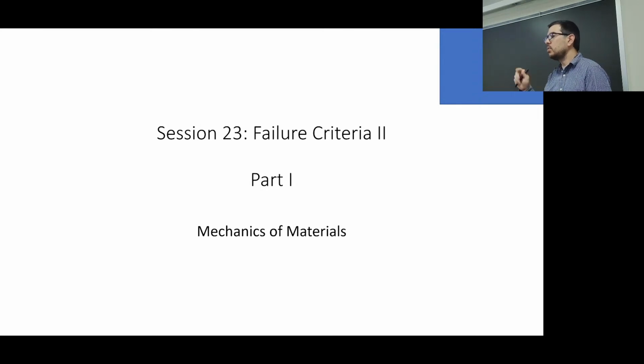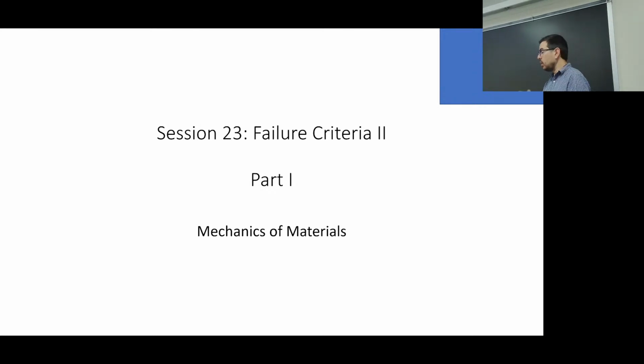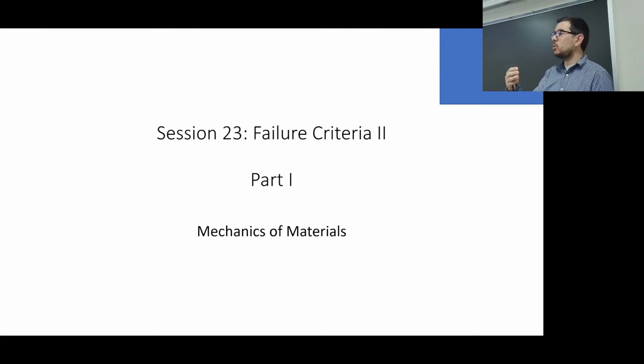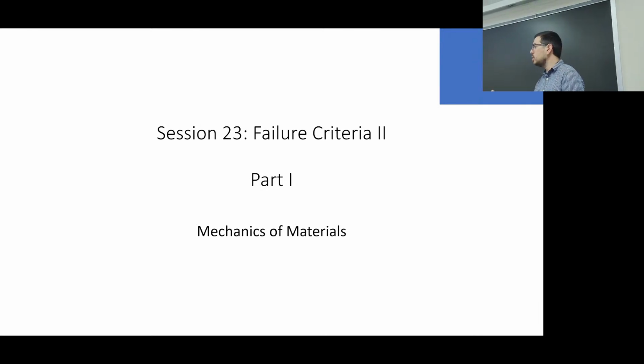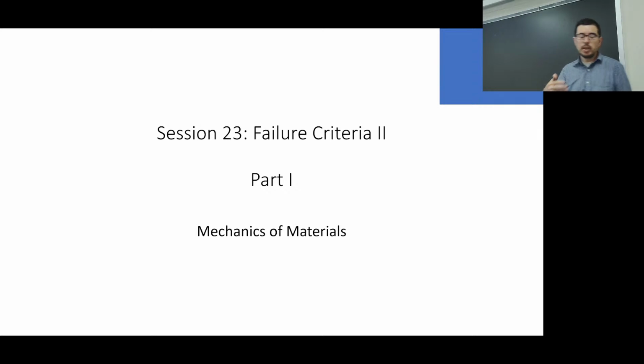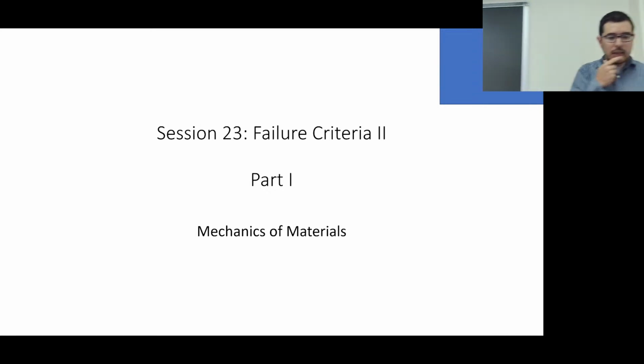So in the box for the maximum normal stress theory, and within the diamond for the maximum shear stress theory, then we're good. The other way to think about it though is quite simply looking at a Mohr circle and saying, okay, if my maximum normal stress is less than whatever the prescribed normal stress might be for maximum normal stress theory, then I'll be okay. And the same thing with maximum shear stress from a Mohr circle, making sure it's less than a threshold.